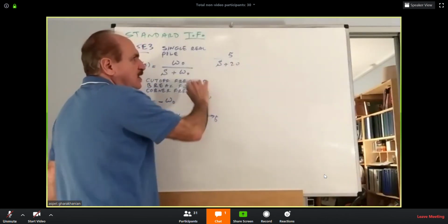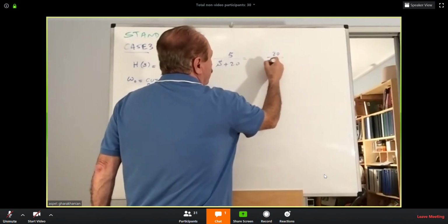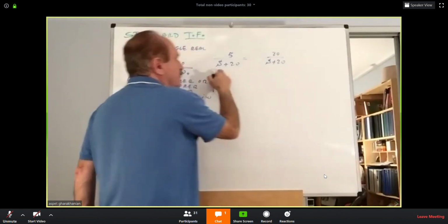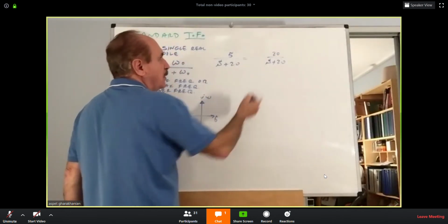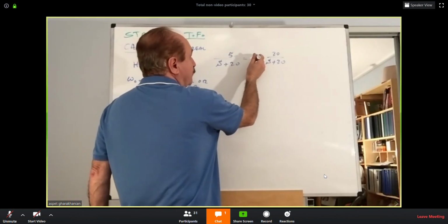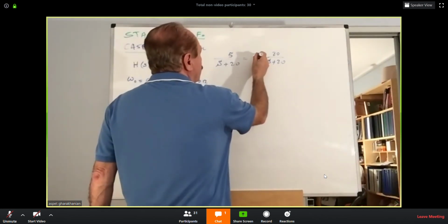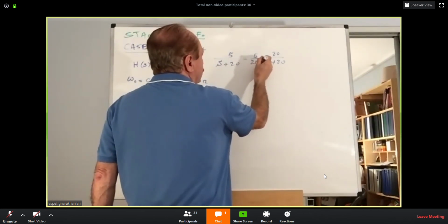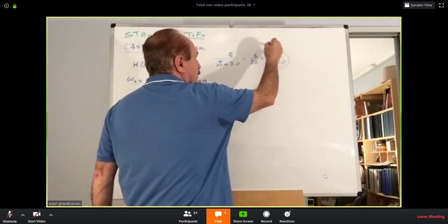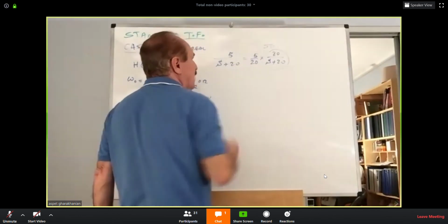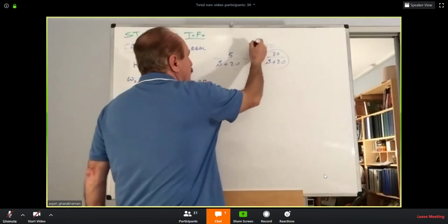So we are going to convert that to a standard form. I'm going to write this as 20 over s plus 20. Look at the denominator, copy that, and put the 20 at the top. But I can't write 5 in here, because if I write 5 there, the balance will be disturbed. So I'm going to write 5/20 here. This is the standard. 5/20 is a number, a quarter, 1/4.